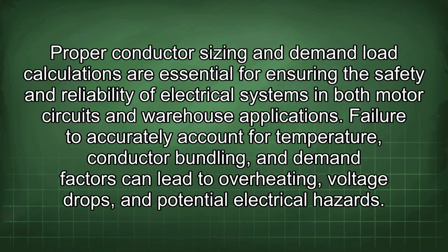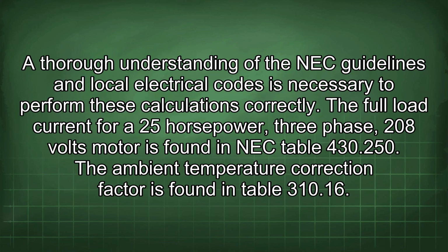Proper conductor sizing and demand load calculations are essential for ensuring the safety and reliability of electrical systems in both motor circuits and warehouse applications. Failure to accurately account for temperature, conductor bundling, and demand factors can lead to overheating, voltage drops, and potential electrical hazards. A thorough understanding of the NEC guidelines and local electrical codes is necessary to perform these calculations correctly.